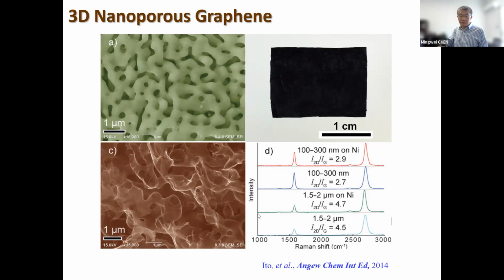features here. Because we grow those samples by CVD, they can be a pretty large size, directly getting into the bulk. For example, I show one example here. We can get samples of tens of centimeters in diameter, with the thickness tunable from 10 micron to 100 micron, depending on your CVD system. You also can control the CVD growth conditions, the temperature and time. So actually you can get monolayer graphene or few-layer graphene.